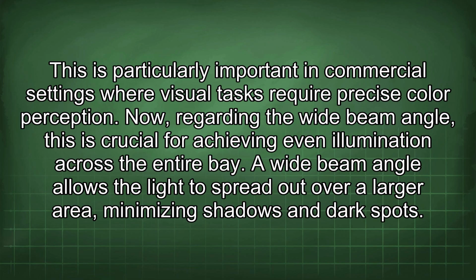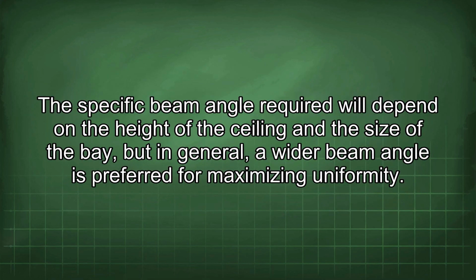Now, regarding the wide beam angle, this is crucial for achieving even illumination across the entire bay. A wide beam angle allows the light to spread out over a larger area, minimizing shadows and dark spots. The specific beam angle required will depend on the height of the ceiling and the size of the bay, but in general, a wider beam angle is preferred for maximizing uniformity.